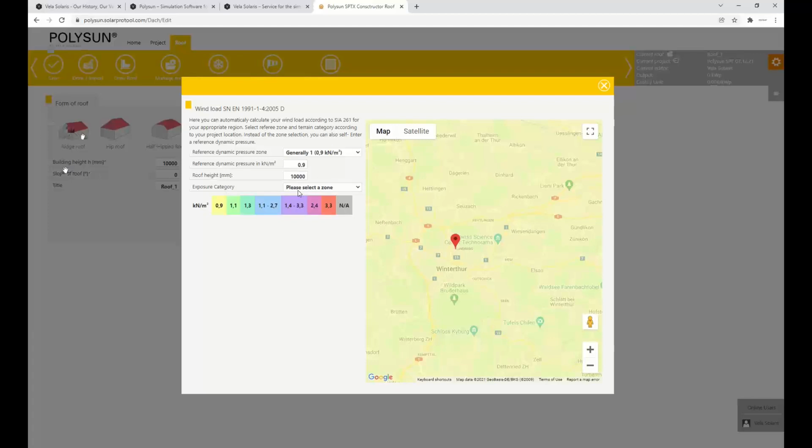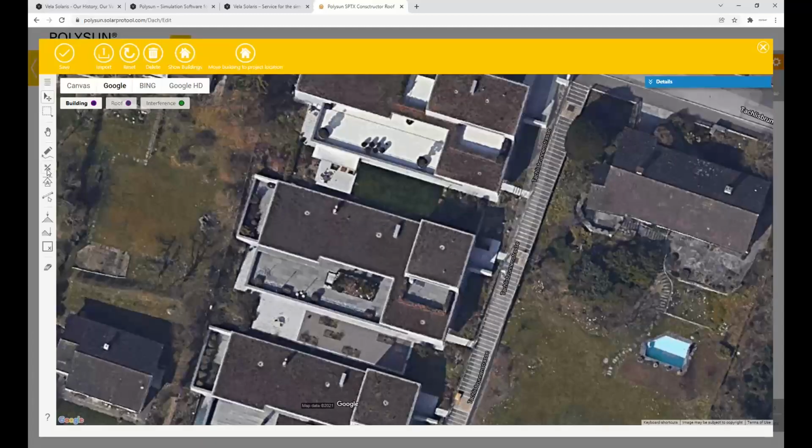Here. And the easiest way to start drawing a building is using guiding lines. If you use more guiding lines, later on it gets easier to get the shape of the building you actually need. So let me start with that. I will select the guiding line tool here on the left side and then simply connect the edges of the building. And whenever you press and hold down Shift while drawing, the line automatically snaps in a 90-degree angle. So this helps us to get nice shapes in an easy manner.